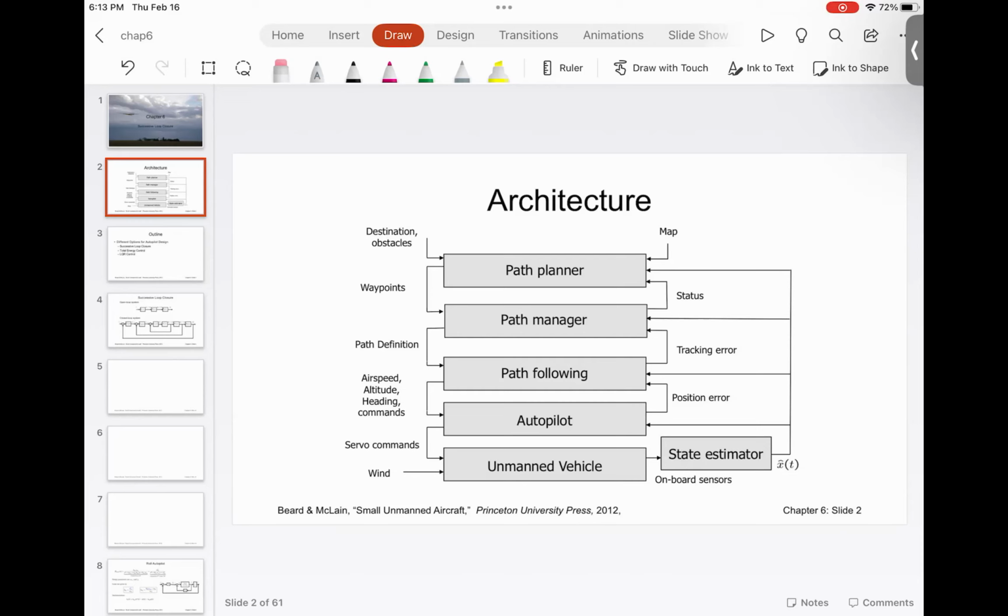So once this loop is complete, then we go to a next level, which is the path following. So basically we give point A and point B. Following the path for the aircraft is very important. It is exactly similar to the trajectory planning that we studied in Robotics 1. In Robotics 1, we talked about how a robot end effector can go from point A to point B. In aircraft, we are doing exactly the same thing, but instead of the end effector, now we have a flying aircraft, which means we have many degrees of freedom that we can control.